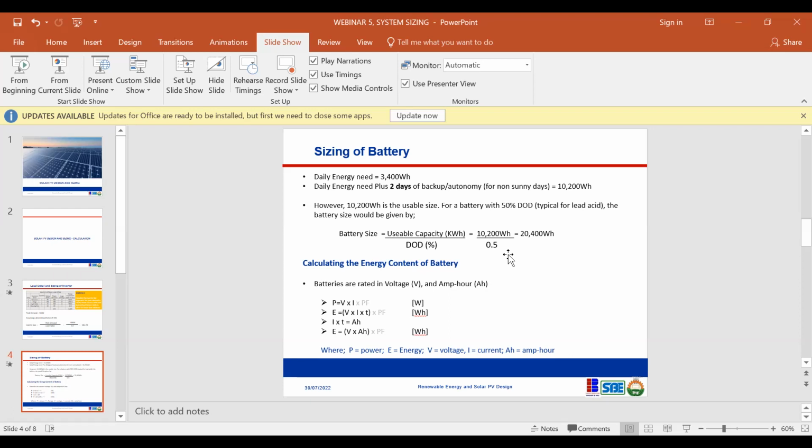Okay. Yes. So the deep cycle you're talking about is lead acid. We also have the lithium-ion battery. In the lithium-ion battery, you also have different chemistry. There's lithium iron phosphate, which is the main one that lasts longer. There is another one, I think it's NCM, nickel, cobalt, manganese. It's still lithium-ion, but it has a lower number of life cycles compared to lithium iron phosphate. So there are different chemistries, there are different technologies in battery.